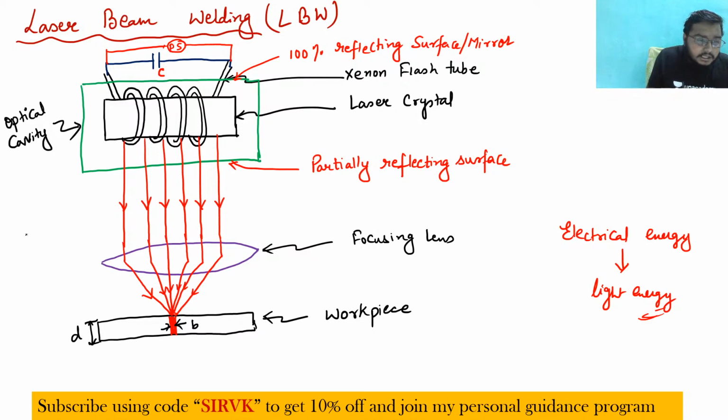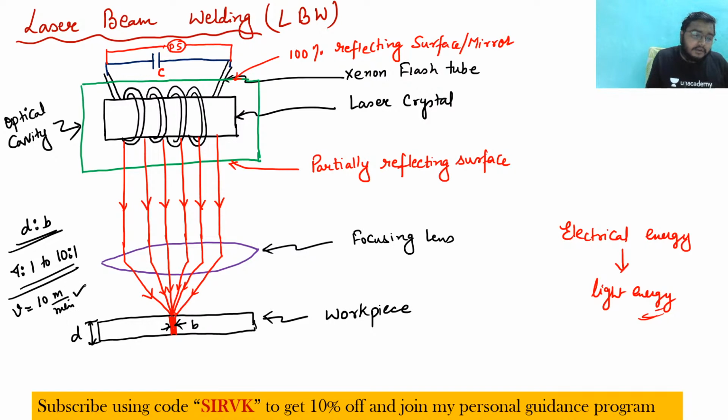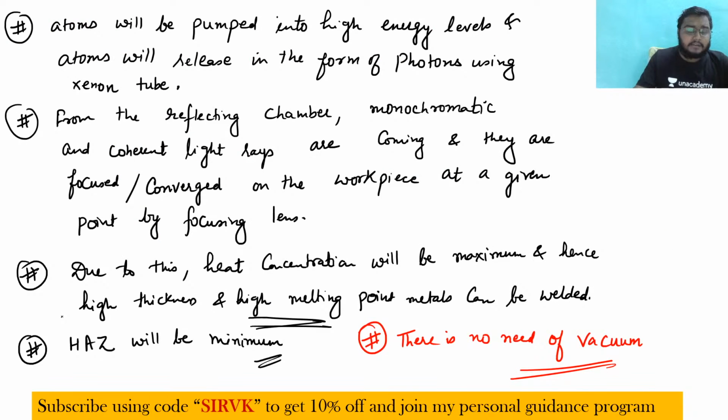Here in this case, the D to B ratio is 4:1 to 10:1, and the welding velocity is about 10 meters per minute. The same velocity in electron beam welding was also 10 meters per minute, and in this case also 10 meters per minute.